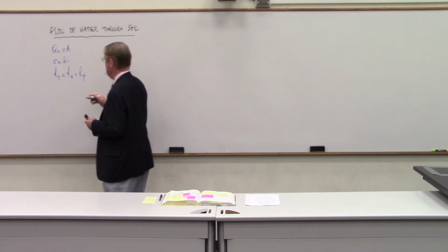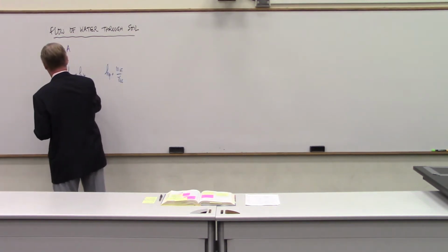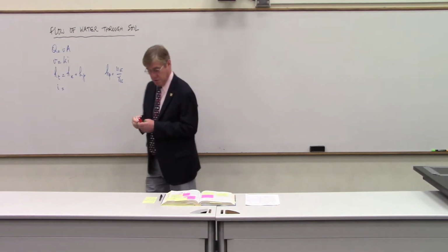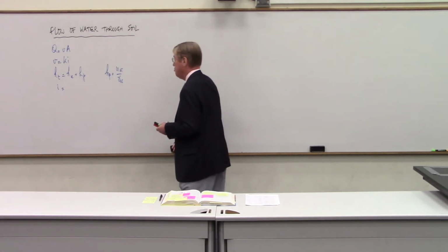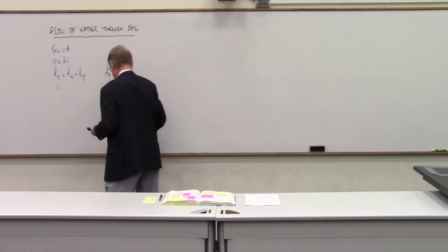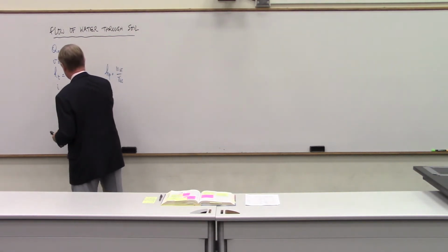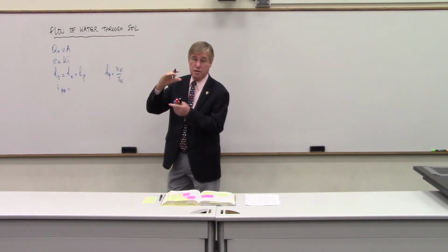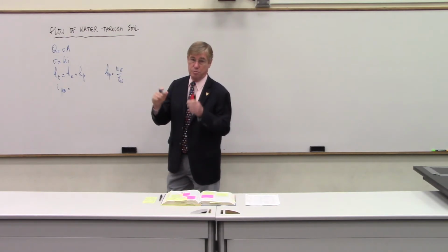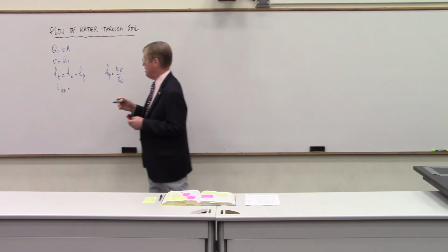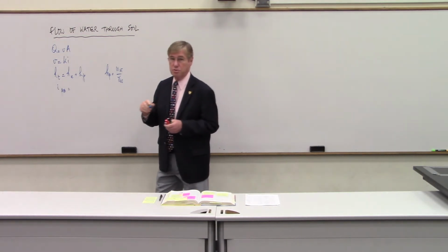And then the last one to remember is the hydraulic gradient. The hydraulic gradient is defined between 2 points. A gradient, it's a slope if you wish. So we define that between 2 points, A and B. And this hydraulic gradient is the ratio of the loss of total head between those 2 points as the water flows from one point to another, divided by the length traveled to go from one point to the other.